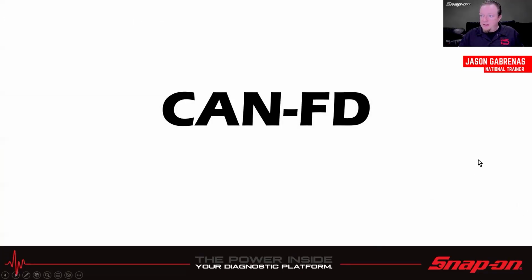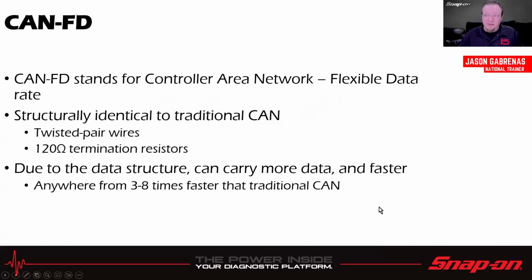Now let's talk about CAN FD. So CAN FD is kind of the newer version of CAN that's out there. Some manufacturers use it. Many manufacturers use it internally on the vehicle. It doesn't terminate out to the DLC. Sometimes it does, but most of the time it doesn't.